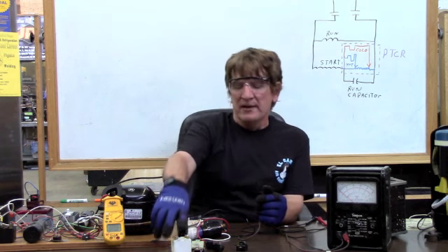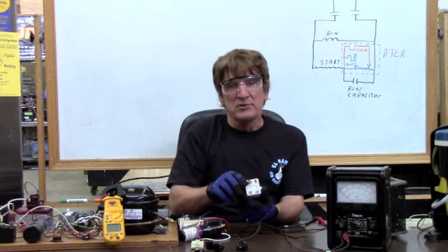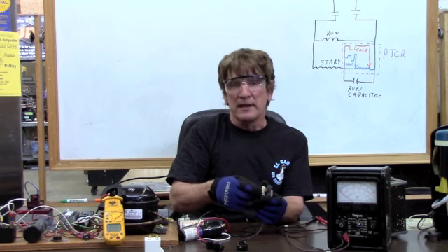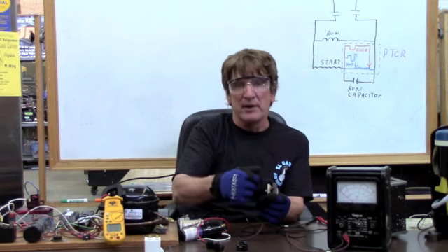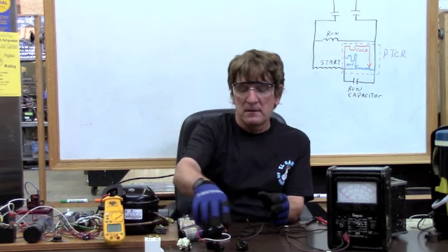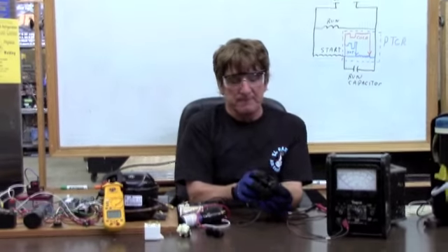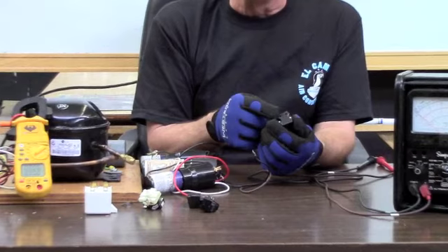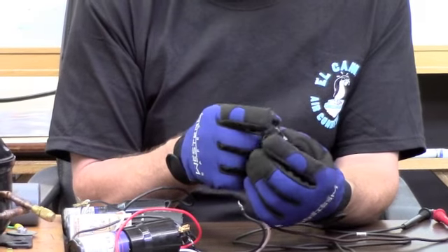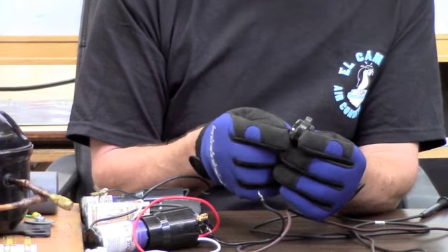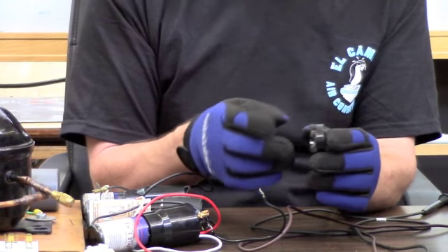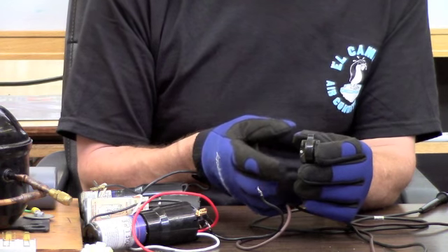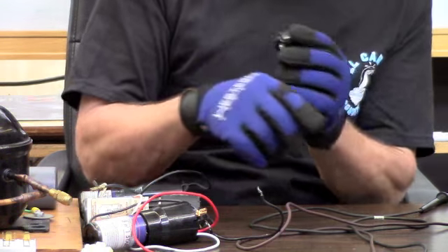We've studied in past videos potential relays, current relays, easily identified by size and by the windings, and we look at PTCs. PTCs have two connections on them. One is where I connect to the run winding, and the other one is the start. And I'll have one or two leads on the back side. When the PTC is cold, the resistance between these two points, between the wire for the run winding comes in and the start, is very, very small.